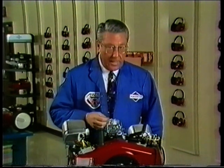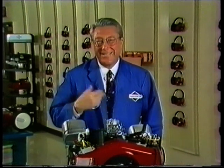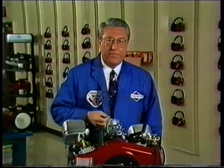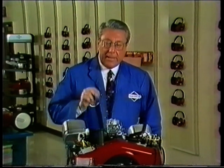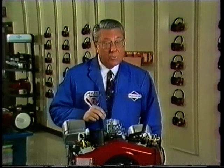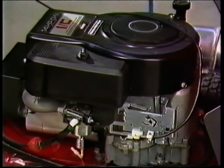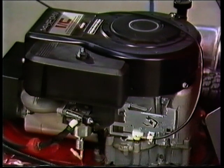Of course, there are times when problems don't fall into nice, neat categories. Sometimes an engine will exhibit multiple symptoms. Here again, your understanding of carburetor theory will play a large part in your success. For example, let's consider an engine which hunts and surges at idle and top no-load speed, but runs well under load.